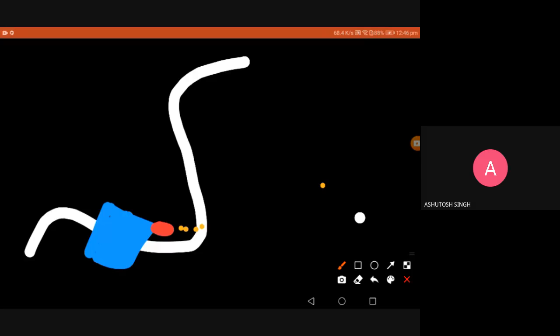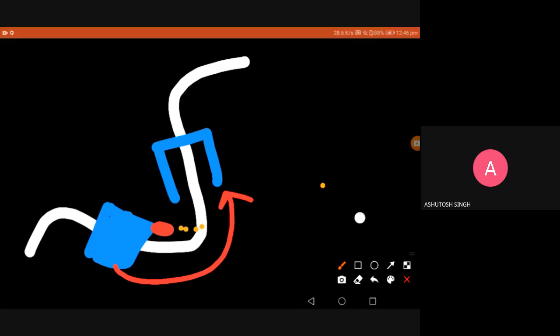I should stop my left motor. When I stop my left motor, my right motor is going to turn the robot towards the left side. Now my robot is turning left, and it is reaching the straight line. As it goes on, after some time in this direction, my right sensor is going to sense some white line. That means I have to turn right. At that time I should turn off my right motor and allow my left motor to rotate continuously. Getting it?